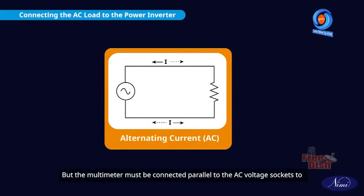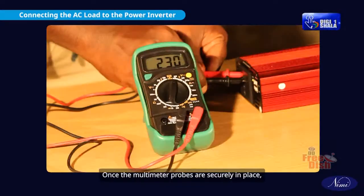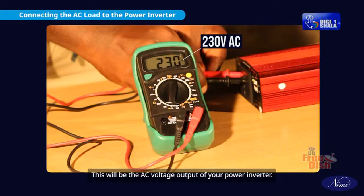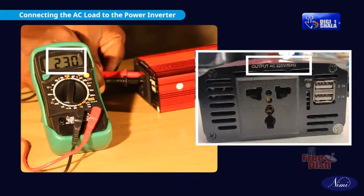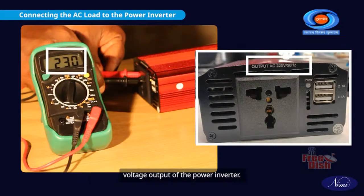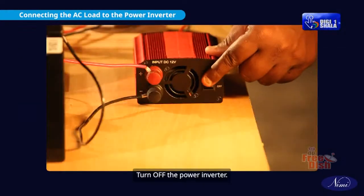But the multimeter must be connected parallel to the AC voltage sockets to measure the output voltage. Once the multimeter probes are securely in place, read the measurement displayed on the multimeter. This will be the AC voltage output of your power inverter. Compare the measured voltage to the expected or rated voltage output of the power inverter. Turn off the power inverter.